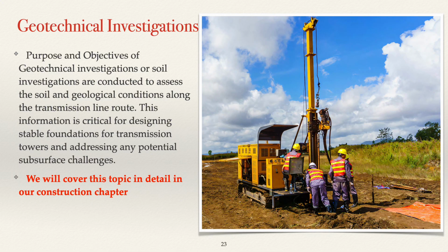Laboratory testing. Collected soil samples are analyzed in a laboratory to identify grain size distribution, plasticity, compressibility, and shear strength. This data helps refine foundation design by providing a deeper understanding of soil behavior under load. Water table assessment. Identifying the water table depth is critical, as high water tables can affect foundation stability and require special design considerations.